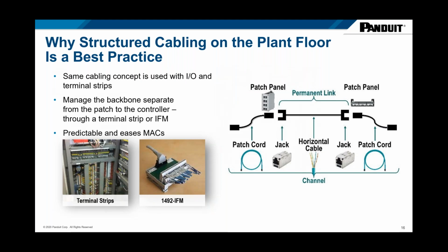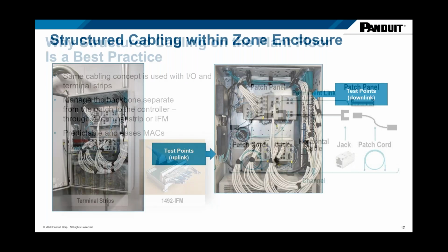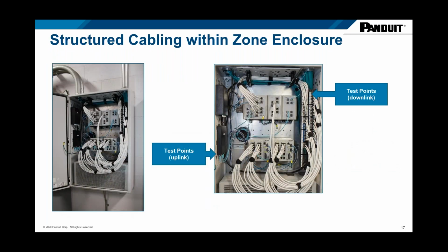And here's a quick look at what that looks like in the field. This is a zone enclosure with access layer or distributor A level switches. So in a moment, we're going to turn the presentation over to Jim. And what we're showing you here, if you look at the diagram, the aqua colored, the thin cable in this image, are the fiber backbone uplinks up to the layer 3 switch in the IDF, and the green cabling that you see in the background there, that's what we were referring to as the horizontal cabling or the downlinks that are connections to control panels or machines.